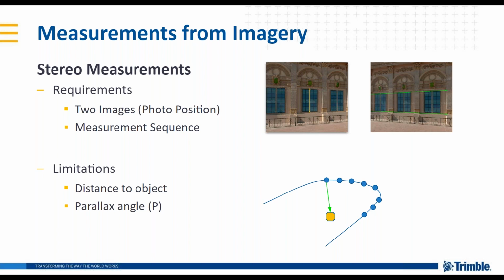The requirement for this step is that you have to do the extraction in the same sequence, meaning if you're extracting a rectangle or a square, you have to do it counterclockwise from both images, keeping the same sequence of picking the vertices. In addition, it's important to know that the limitation of this extraction method is the distance to your object, meaning further objects are going to be represented by fewer pixels, so you'll have more error margin.